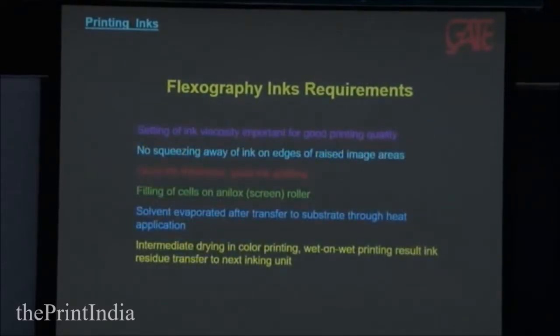Ink requirements. Setting of ink viscosity is very important for printing quality, because if you are using liquid inks, the viscosity will change continuously, especially in solvent-based inks, and if there is no temperature control, then it's a disaster. There should be no squeezing away of ink on the edges of the raised image. Now, in flexography, typically, we have been talking about the characteristic dark outline.